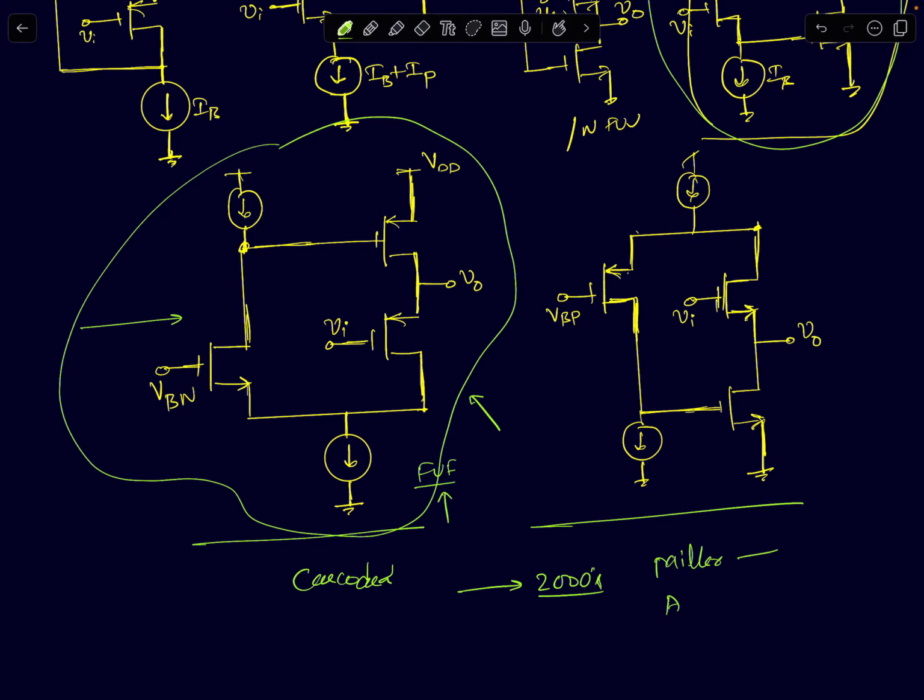We had advanced versions of Miller called the nested Miller compensation technique. Then Ahuja was also thoroughly analyzed in that decade, I would say. And then we had dominant pole compensation and non-dominant pole compensation and feed-forward compensation. All these compensation techniques were very intuitively explored during that decade, to great detail. And someday when I offer an LDO course, I'll cover the history of all of that, and then you can see how well the field itself evolved.